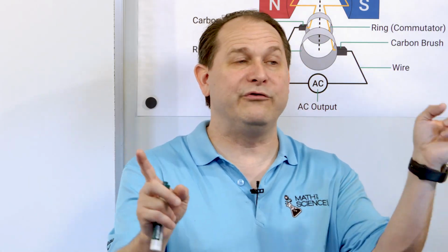We're turning a coil of wire in a magnetic field. It's exactly the opposite of a motor. A motor, you turn on the electricity and then you force the thing to turn inside of the magnetic field. For a generator, you do it backwards. You turn the wire through some mechanical thing like a hydroelectric or nuclear plant, and then that generates what they call an EMF, electromotive force, which is the same thing as a voltage here.